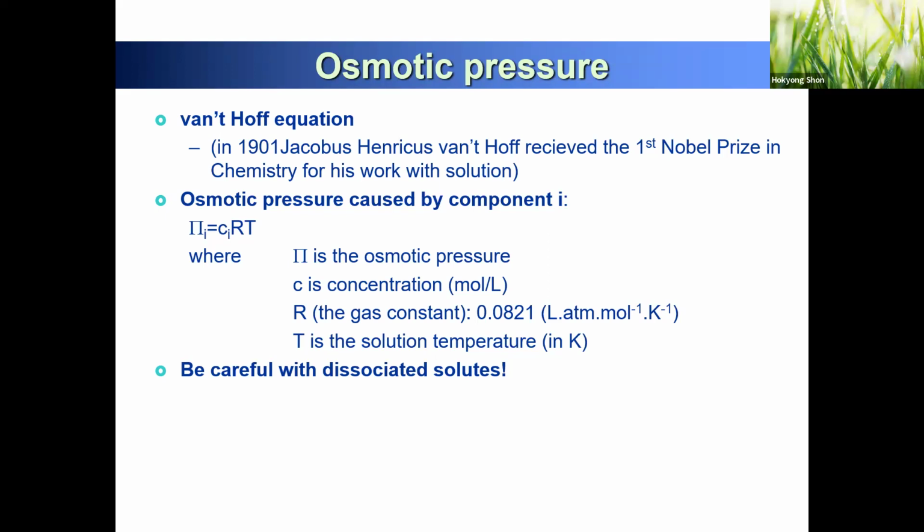But with high temperature, they can move easily. But for osmotic pressure, seawater at 25 degrees versus 10 degrees, high temperature means high osmotic pressure. Which means you have to push your pressure more, which means your water flux is low, right?